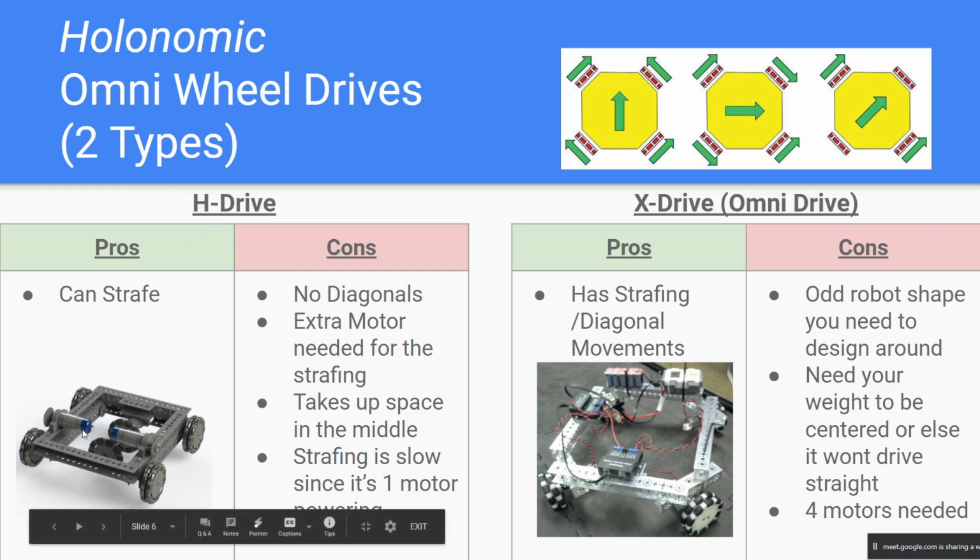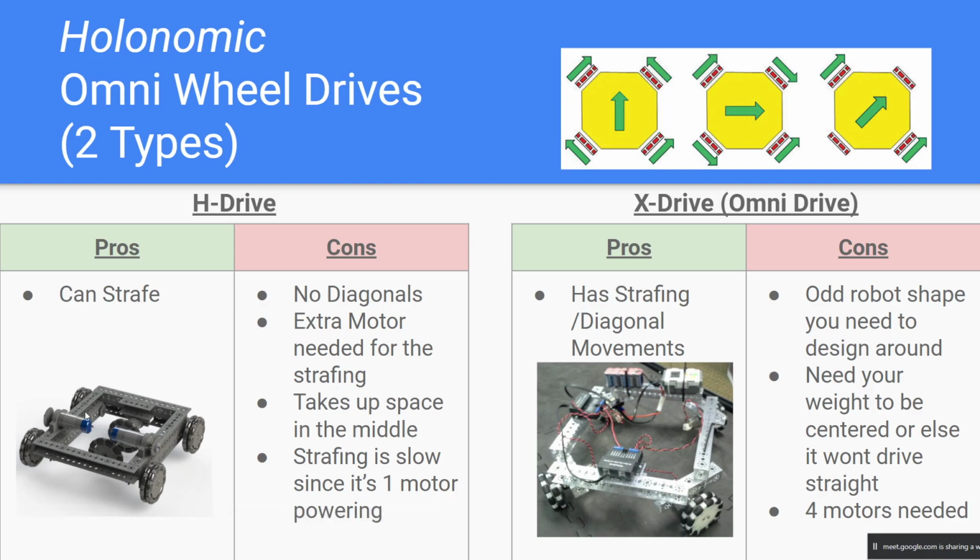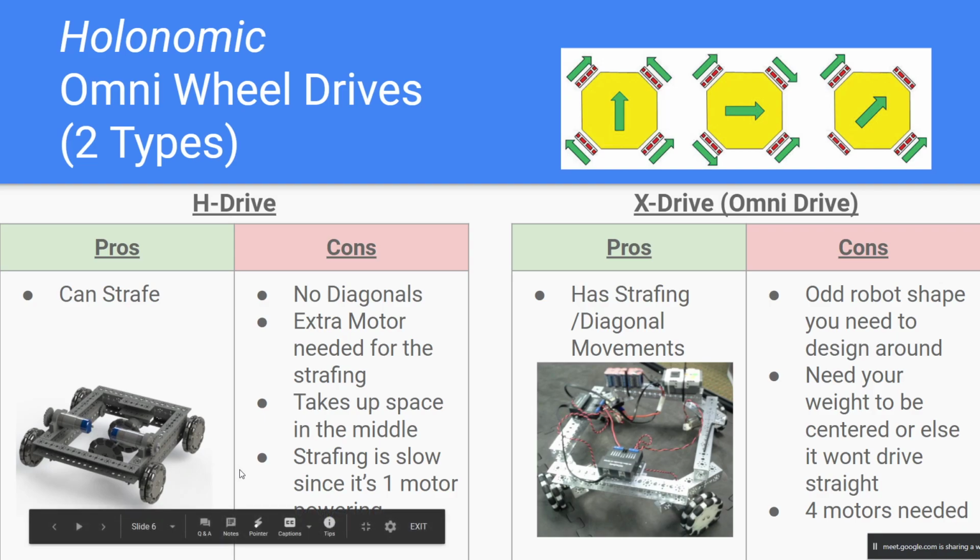So as you can see in this picture right here, there are omni-wheels in the middle, and they're connected to a motor. So this allows the motor to spin those wheels so that you can move sideways. Also keep in mind, the main wheels for the drive are also omni. This is a requirement in order to be able to go left and right, because the rollers will roll you that way. Yeah, there you go.